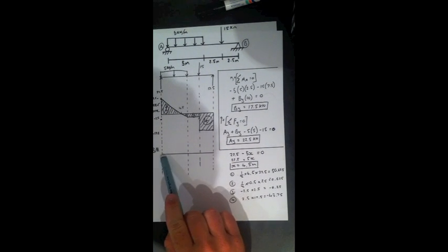So one is simply the area of a triangle, half times the base times the height, half of 4.5, and you've got them all there. I'll save you the calculations, it's not particularly exciting, just the areas of triangles and rectangles. And it's important to get the negatives right, because that can be a problem later. So once we've done that, it's time to draw our bending moment diagram.